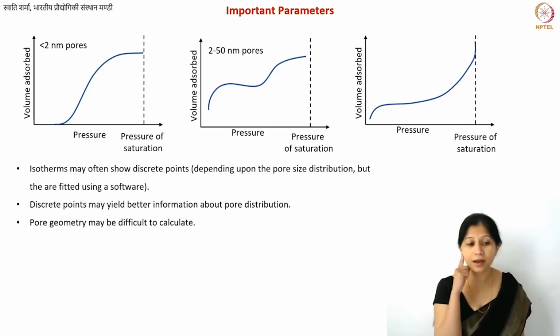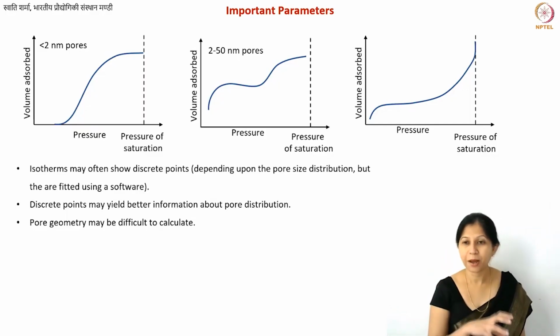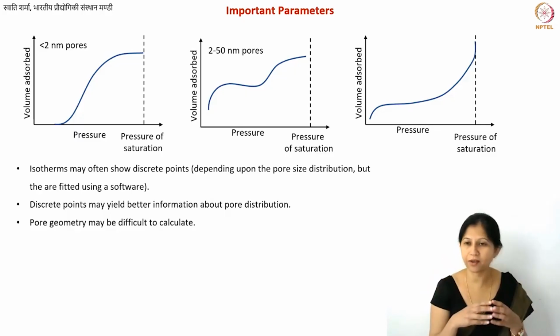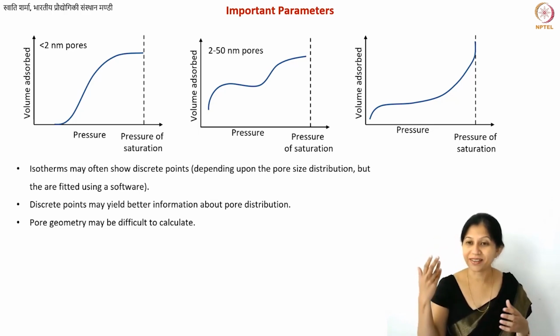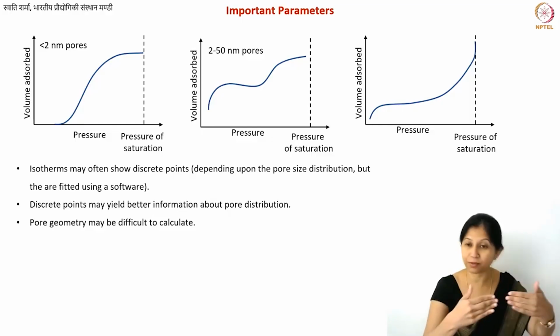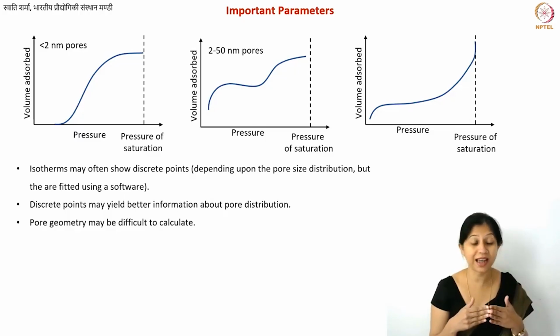By the way, X-ray tomography and MRI are techniques which are challenging, but the advantage of these techniques is that you can also get the information on the closed porosity. You have slices of images. Basically, when you take the MRI of your brain or X-ray of your hand, you don't have to cut open the brain, right? This is non-destructive imaging. That is why these techniques are very useful. These are non-destructive techniques that can also give you the information about closed porosity. So if your material has a lot of closed porosity, you might want to try one of these techniques.